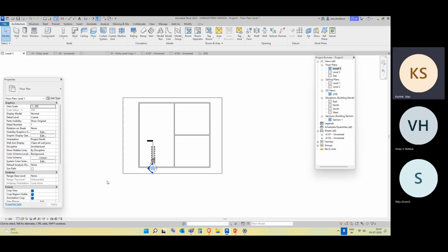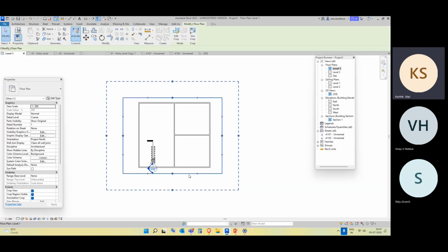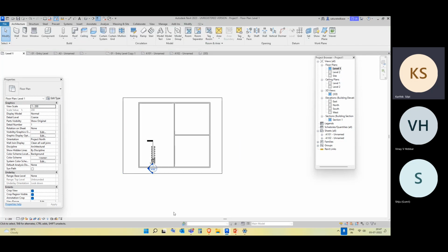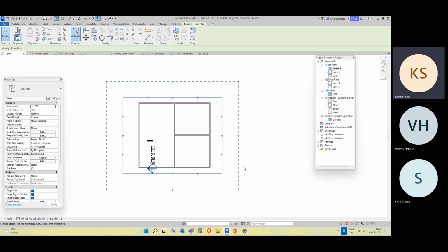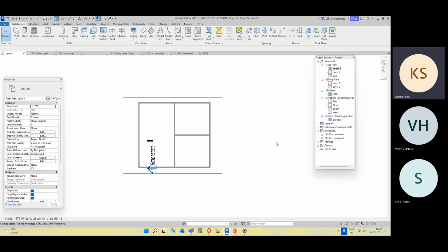Whenever you are going to place annotations, this is going to be a problem. Or if you don't check it in your sheet beforehand, selecting your annotation, that is going to be a problem. So it will take a lot of effort for us to correct and place the proper annotation before going to the sheet. Once for the selected scale, the selected annotation is going to be visible properly, then our job is done. We can just continue with that. But the problem arises when we are having multiple scales for the same drawing in a given scenario, then we have to adjust a bit of the annotations. So that is the one challenge you have to remember.